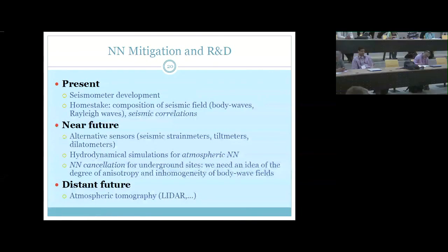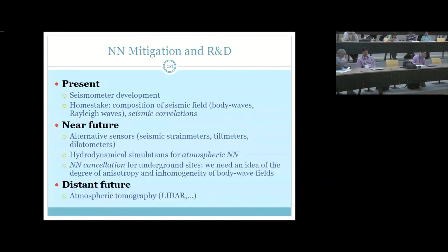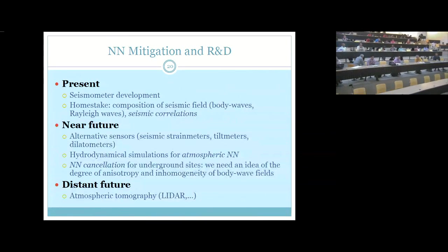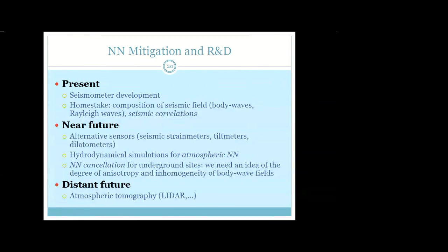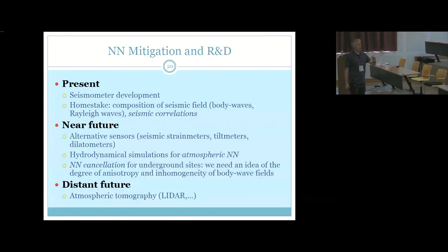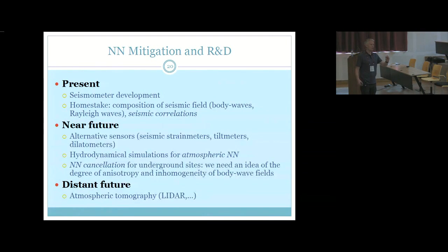So, yes. For the gravity noise, it's a little bit more tricky. But in general, if the soil is very hard and you have a source producing seismic noise, then the amplitude of that noise will be smaller, and you will produce a higher amplitude of seismic noise if the soil is soft. So in that case, you could say hard soil has an advantage because it comes with smaller seismic noise. However, the density will also be higher for that hard soil.